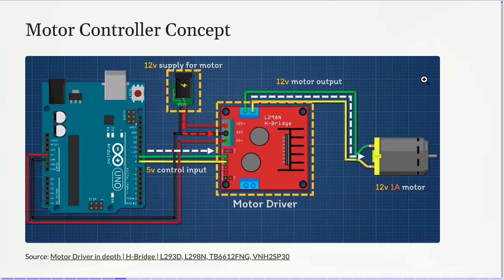We can use this 5 volt to power the Arduino board, if we don't want to power it from external sources. So having one battery connected here to the input is going to provide 12 volt. It will be converted to 5, and this 5 can be used to provide power to the Arduino board.